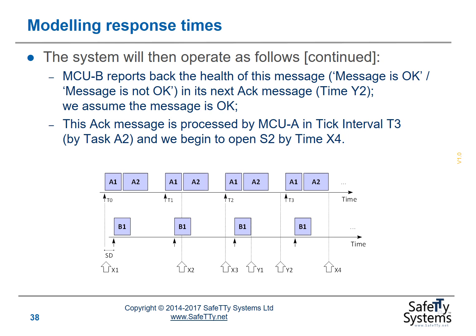We're also assuming that until MCU-A has received confirmation from MCU-B that the message is OK, it won't react to the command in the message. So we're assuming here that the message is OK. This acknowledgement message comes back to MCU-A in tick interval T3, and we then begin to open switch 2 by time x4.